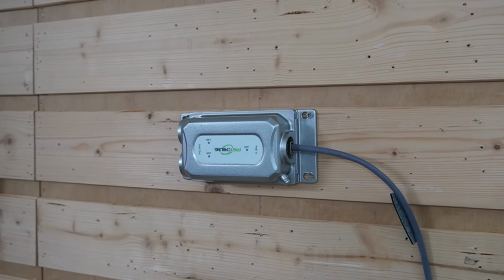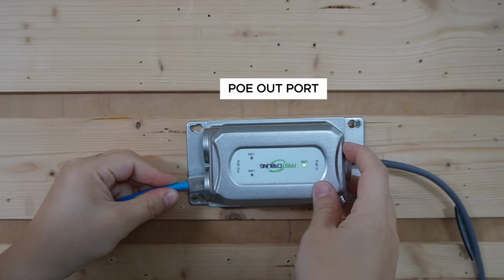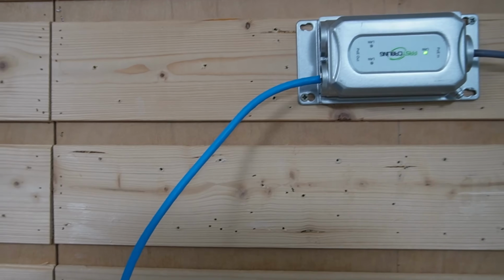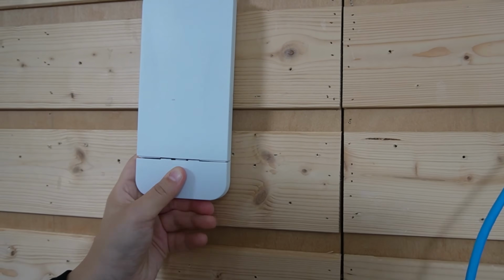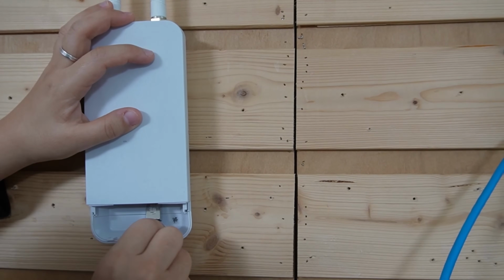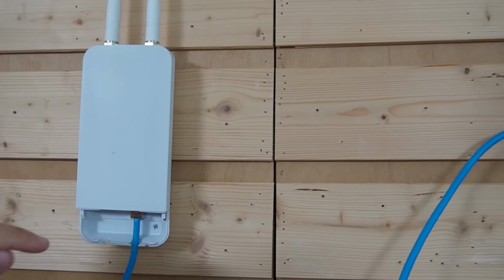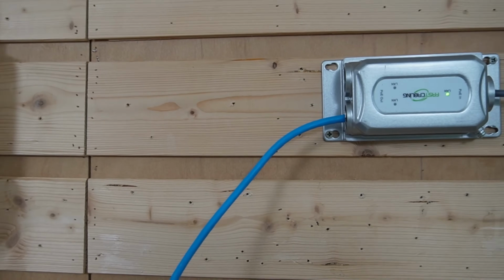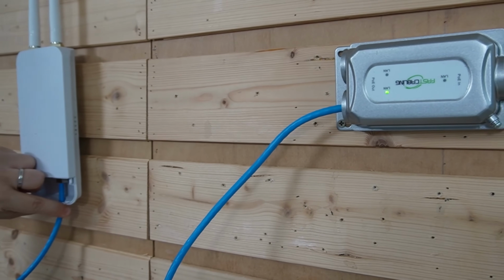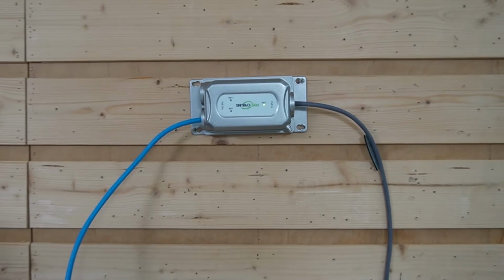Then I'm going to run this 50 meter cable from the PoE output port, either one of them, directly to our Wi-Fi access point. All right, now we can see our Wi-Fi access point is getting both power and data, and the indicator light is on.